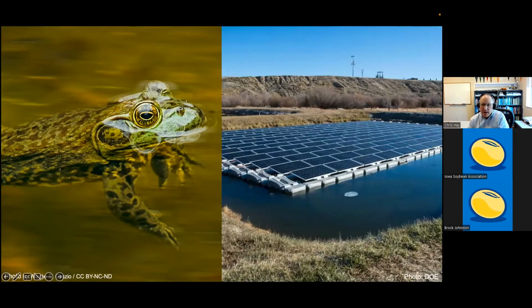And then one that's maybe a little more futuristic, but certainly a possibility as well, is something that's called photovoltaics. So it's actually floating solar panels on top of that storage. And so by having that area where we can put some solar panels and capture that sunlight and convert it to energy, we can actually help produce energy with that system as well, which could be a help as far as some of the pumping energy that may be required for the system as well. And then another benefit is by having those solar panels there shading the water surface, we'll get less evaporation from that water surface, and so we can store more water that way, or reduce the losses of the water that we do store.